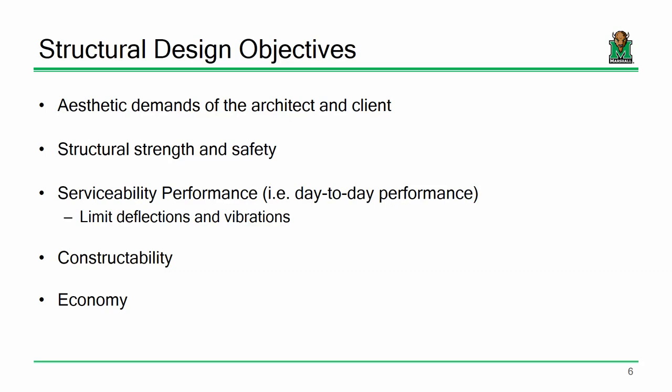If you've got some massive steel girder that has to support some concrete deck or something, many times the worst case scenario for the stresses on that girder is before the deck's even placed. Once the deck's placed, the deck's locked in and the bridge isn't going anywhere. But a lot of times we're actually taking the flanges and making them thicker, taking the girders and making them deeper because of its performance during construction, not in the intact final state.